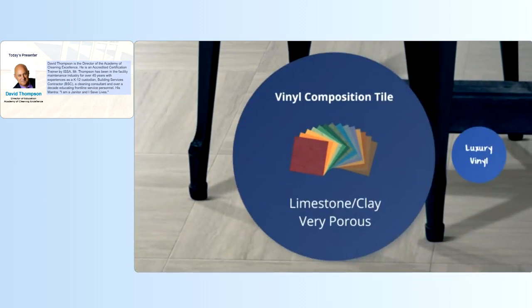So let's review a little bit about what these products really are. I think this is something that's very interesting that you have to understand, is that vinyl composition tile, which has been around since the 1920s, is predominantly made of limestone and clay. Now, it's only about 12% vinyl, which means that this is a very, very porous floor. And this is why we have to use a coating on it. If we didn't, you couldn't clean it. You couldn't maintain it. It wouldn't last. So this is why coatings, what we call wax or floor finish, is a necessity on vinyl composition floor.